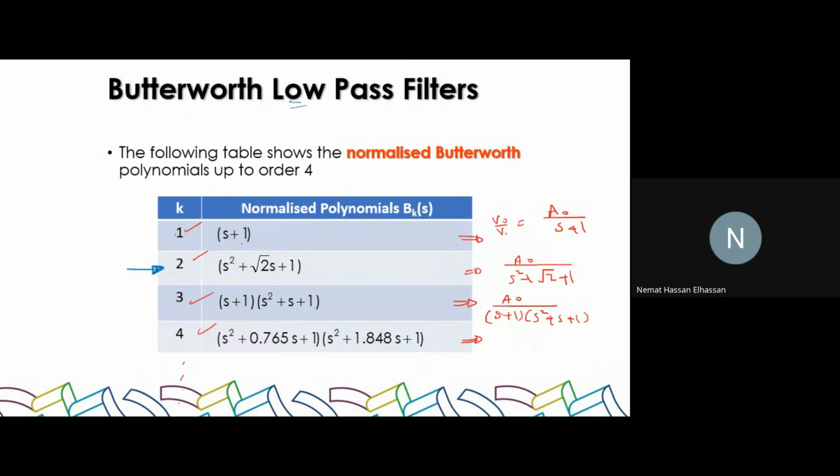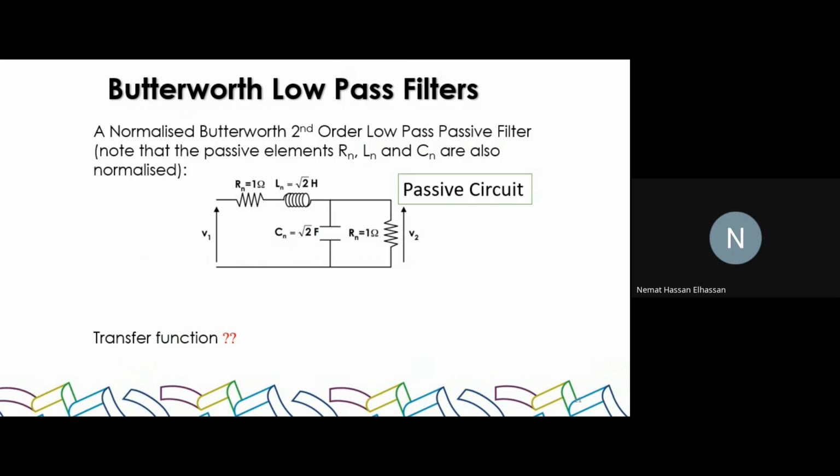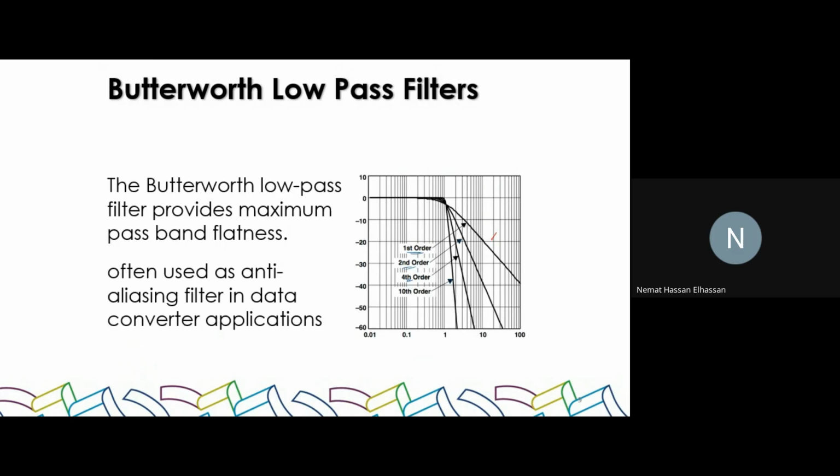So this circuit is in fact a second order low pass filter. And therefore, even without plotting, we know that this curve represents the normalized frequency response for it, right? So knowing that, if you know the transfer function, you can find the circuit that will fit this transfer function, which makes your work as a designer a whole lot easier, right? So let's keep that in mind.